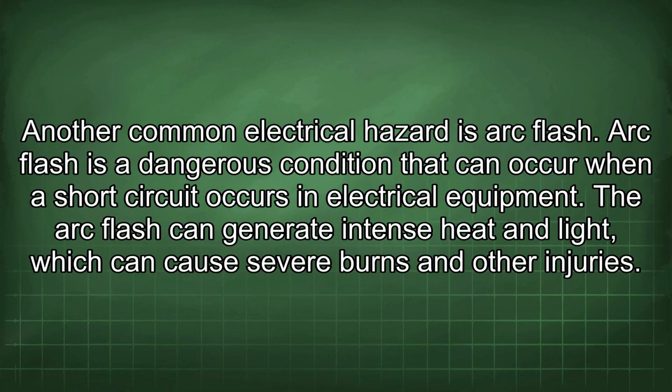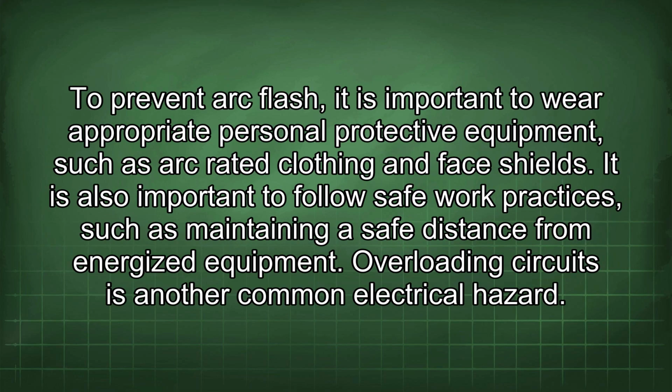Another common electrical hazard is arc flash. Arc flash is a dangerous condition that can occur when a short circuit occurs in electrical equipment. The arc flash can generate intense heat and light, which can cause severe burns and other injuries. To prevent arc flash, it is important to wear appropriate personal protective equipment, such as arc-rated clothing and face shields. It is also important to follow safe work practices, such as maintaining a safe distance from energized equipment.